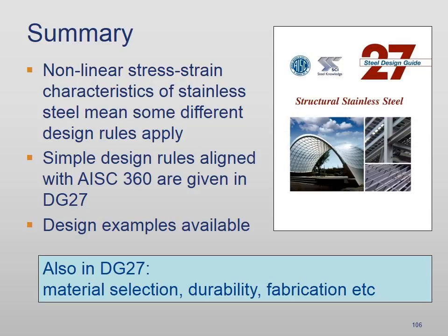But I do want to point out that often what is listed in any of the ASTM standards is the minimum for a very heavy section. And lighter sections are typically quite a bit stronger. And there is discussion currently within ASTM of possibly showing gradations for these hot-rolled sections. So you may see that in the future. Okay, thank you.